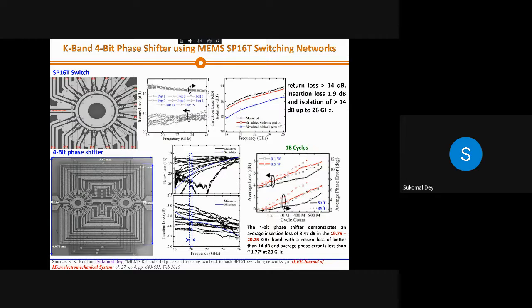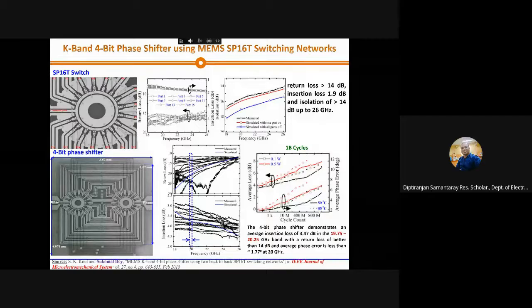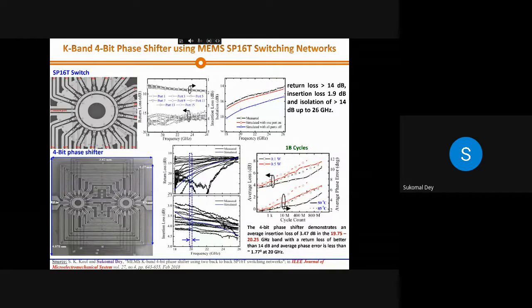Means we have to check the power, sir. See, absolutely correct. The point here is that power is basically a function of temperature. Right? So if you are satisfied with the 85 degrees Celsius temperature, and your device can sustain 85 degrees Celsius, then obviously at 25 degrees Celsius this device can work with 1 watt of power.